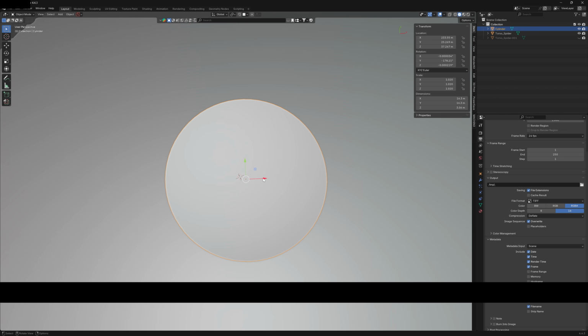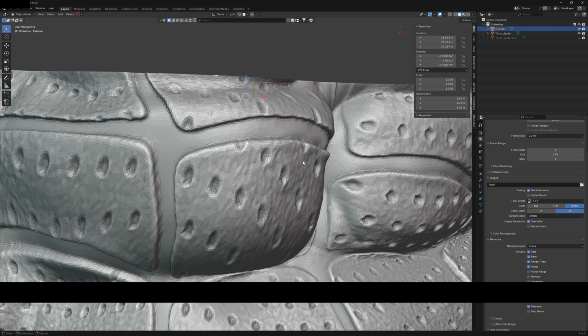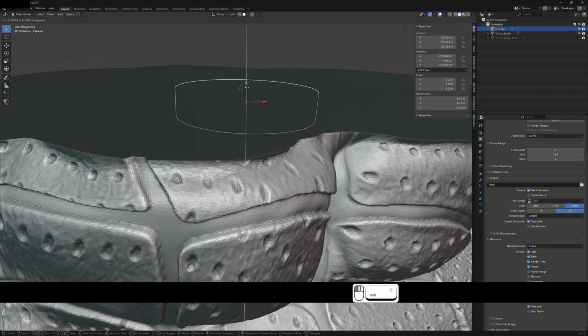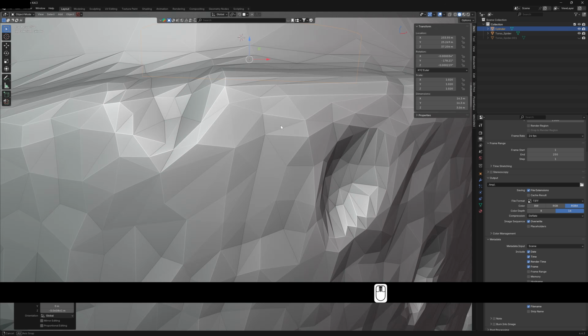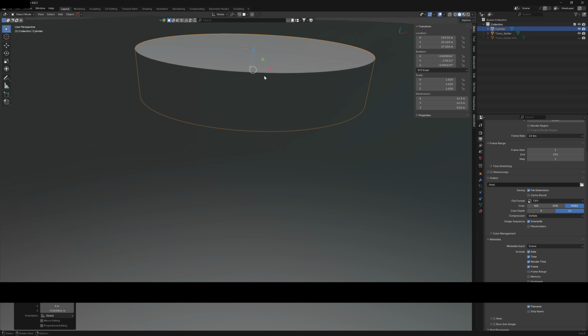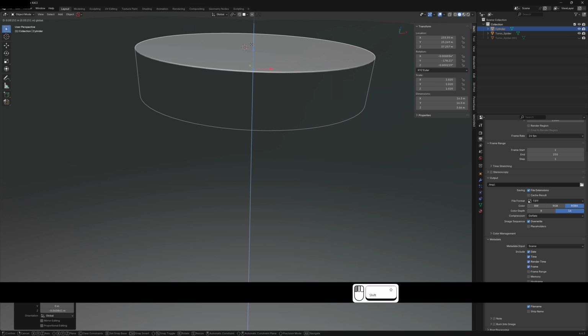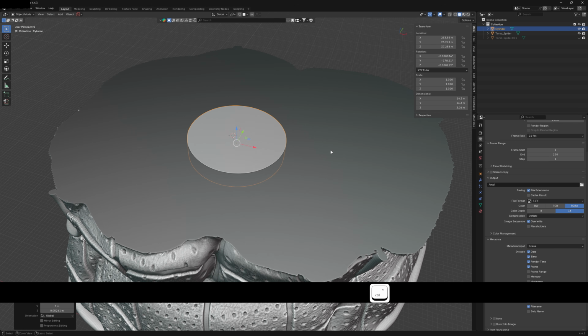So that it's going to be big enough to fit your magnet. And you'd be thinking, okay, well, I'll put that down there. Well, actually, that's going to be a bit too deep, because you've got the tolerance at the top and the tolerance at the bottom. So your magnet will actually sit down 2 times the tolerance, if you know what I mean. So just raise that up a tiny touch, and let's just duplicate.